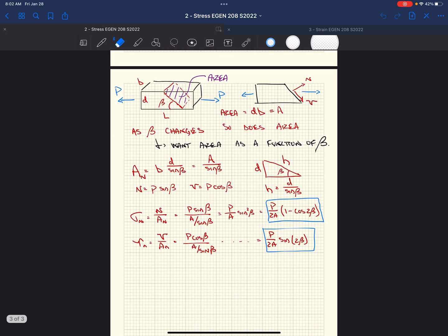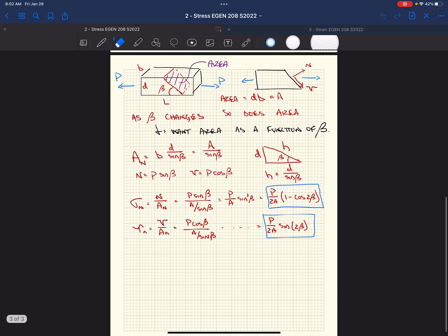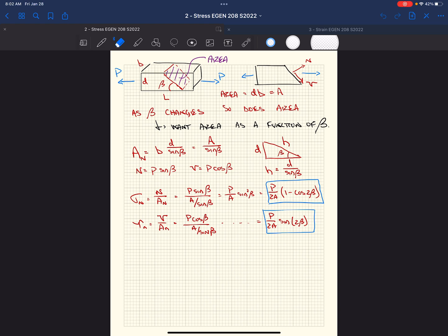And then we noted that as this cross section, that surface, moves from completely perpendicular to completely horizontal, the area of that cross section changes, and stress is force over an area, so we need to account for that based on that angle. And so we came up with a couple equations that gave us our stress based on this force with respect to our given beta angle, as well as the area of the surface over which that acts, whether the force is in shear or in a normal force. We got a sigma n or a tau n for our normal and shear stress.